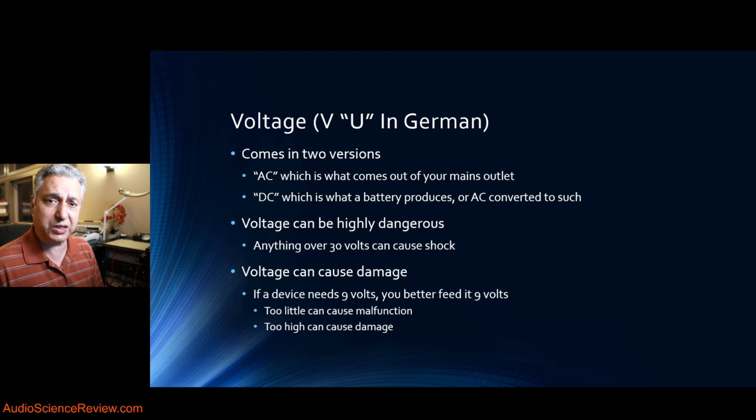The other part about voltage is that it can cause serious damage to the equipment if you feed it too high a voltage. So let's say you have a DAC or something runs with 9-volt power supply, external one, and you replace that with a 12-volt or 15-volt or 20-volt. It might work. It might work and run hot and die soon, or it may just damage it immediately. So it is extremely important that if you're going to change a power supply or mess with something there, that you match the voltages. That if the device says I want 9-volt, you give it 9-volt.